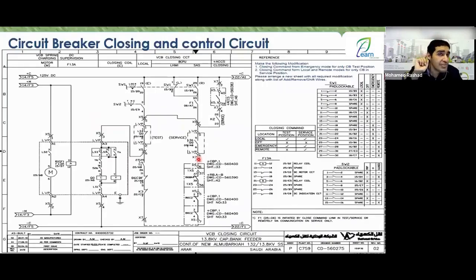Okay, normally closed relative to what? We must return to the normal state. Any auxiliary relay, any trip relay, any lockout relay, any contactor drawn in your official diagram is depicted in the state of being de-energized. Without power, not energized. Is that clear? So its contacts are such that when it operates, it opens this contact.